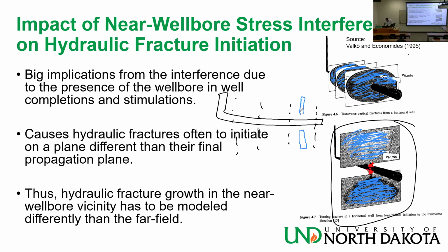But in the well, and this is blue, is transverse, is coming out towards me, out of the screen. But the longitudinal components can be pretty wide, right? It can very easily extend beyond the length of the stage into another stage. By the way, when we say I'm stimulating in stages, I isolate the stage, the part of the wellbore I want to stimulate with packers, and then I pump fluid, so it only goes through those perforations.